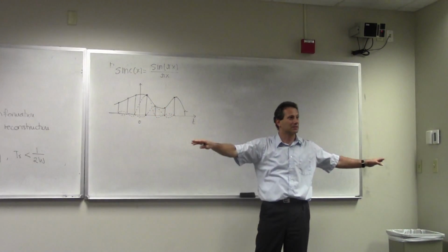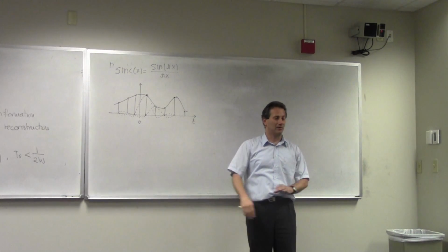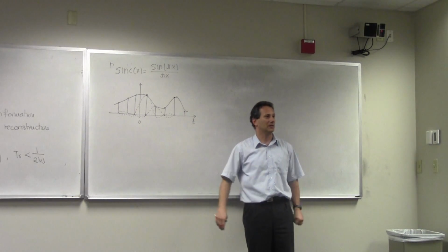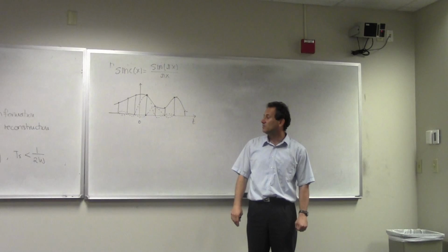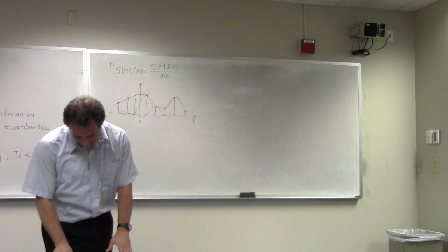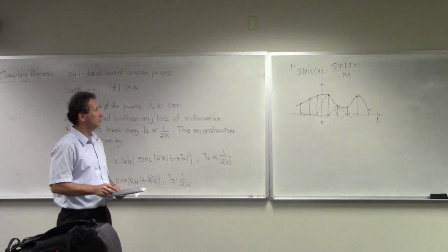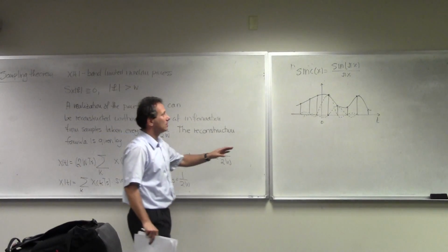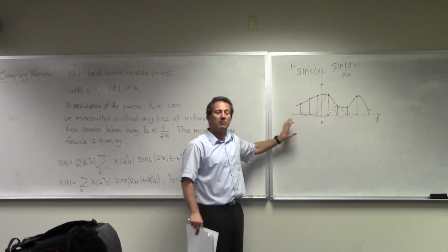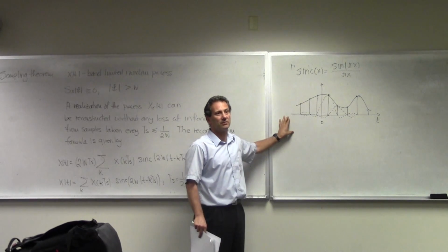Fortunately, the tails decrease as the time goes by, so we can say, well, you don't need infinitely many samples. We can probably truncate the sinc after the 10th sample, and it will not be of any significant impact. But still, if you are a mathematician, that would bother you for the rest of your life. It doesn't bother us much, because we know that at some point you need to engineer it. So be aware, this gives us a tool, gives us a comfort level theoretically, but in every practical application, we're going to have to figure out a way how we reconstruct the signal from its samples.